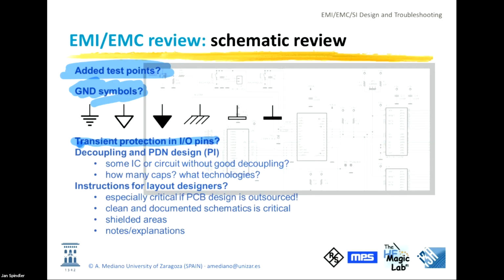Another important topic, decoupling. Check that all integrated circuits, all the important circuits like switching devices, drivers, power amplifiers, in audio or in high-speed digital circuits, have some kind of bypass or decoupling capacitor. How many capacitors? What technologies?